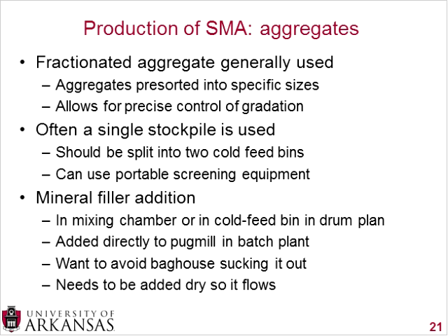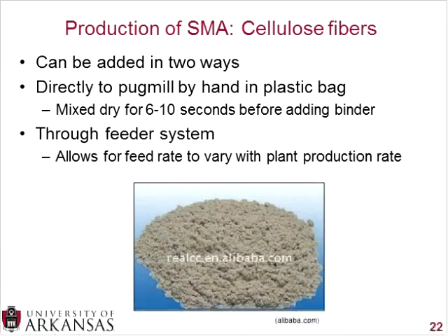Another reason that you want to be a little bit careful is that it does need to be added dry. You want no moisture in your mineral fillers. Because it's dry, that means it'll kick up more, but you also want to make sure that it's able to flow over the other aggregate and mix nicely with the asphalt cement. So you want absolutely no moisture in there. That's for the mineral fillers and the aggregates.